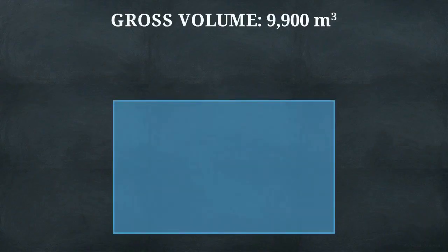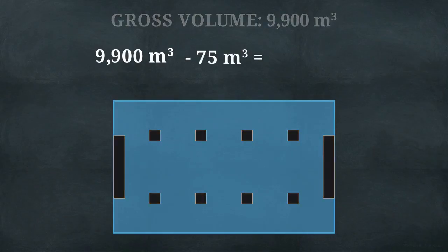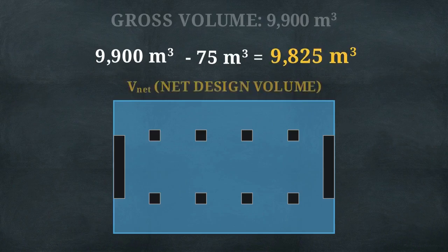From this gross volume, we subtract impermeable solids. These are permanent, perfectly sealed objects that displace the gas. In this data hall, the structural concrete columns and sealed perimeter structural bulkheads amount to precisely 75 cubic meters of displaced air. Subtracting this from the gross volume refines the calculation.